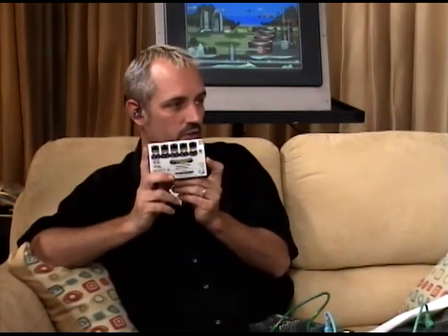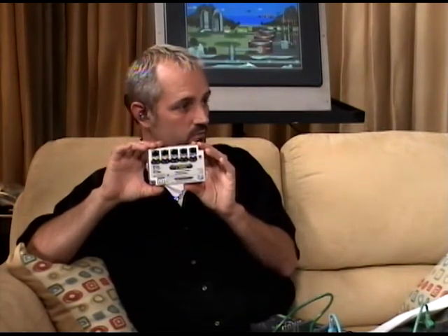People asked, why should I buy that? Well, of course, we have to give them the switch versus hub, but also the ruggedness. Vibration was one of the biggest killers of hubs. You can put a standard Ethernet hub in your cabinet, but if you've got a machine that's hopping around or vibrating or humming, it's going to come apart. Whereas these are actually made to withstand vibration and high temperature. And for those applications where you can use a simple type Ethernet hub, we do carry that. We do sell that with the cables too.